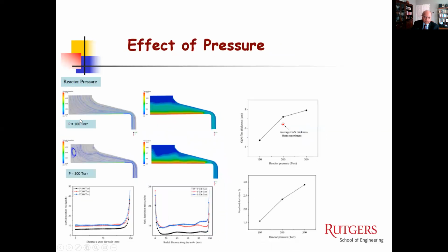You can look at the pressure again, going up to a higher pressure. Look at this, it starts giving disturbances. So at high pressure, the quality is bad. The deposition rate is higher. So increase the pressure, deposition rate higher. Increase the concentration, deposition rate higher. But at the same time, your quality becomes lower. And you can see this. The quality becomes lower as you increase the pressure.